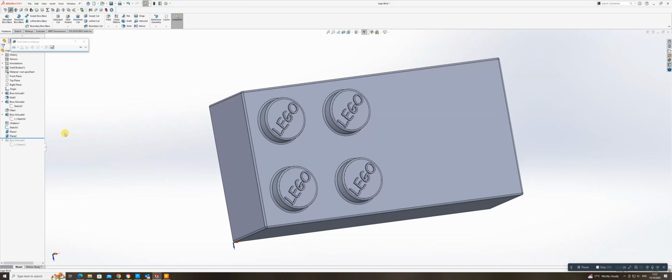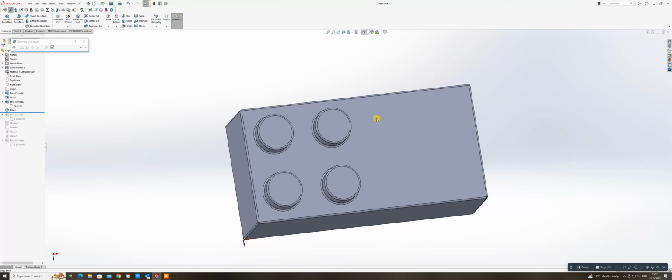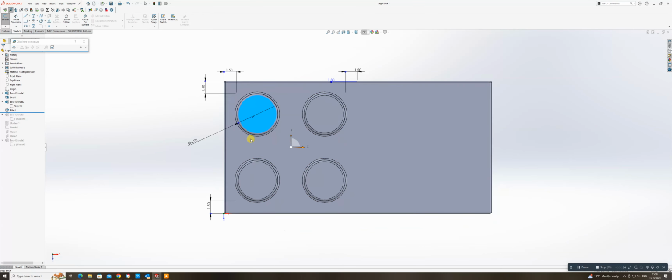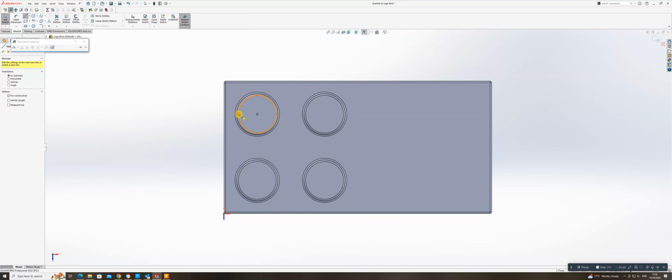So to start with, what I am going to do is take my history tree here, take it back up to where we've got no text at all, and I'm just going to repeat what I did here for you. I also need to put in some planes as well, just to help. Well, actually I don't need to put planes in, sorry, that's not right. What I need to do here is go to sketch and try to get the position of the Lego word there, and I'm going to have a centre line from say there to there. That just gives me a datum to go for.